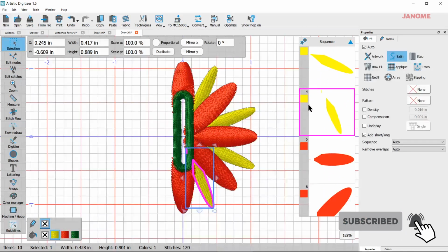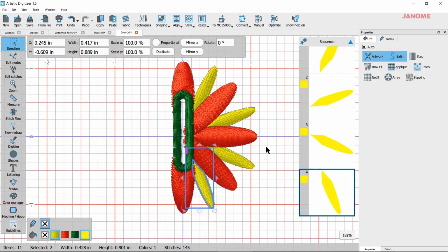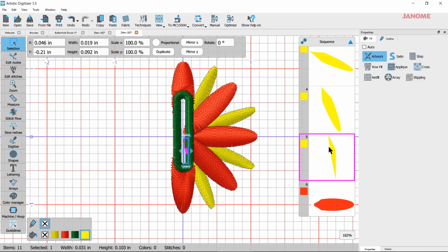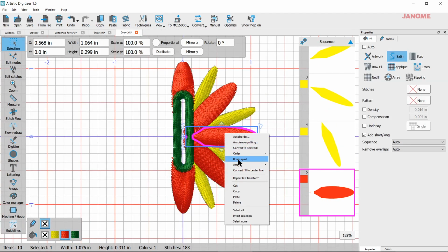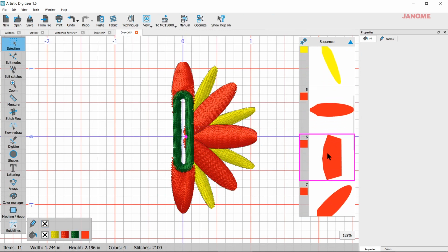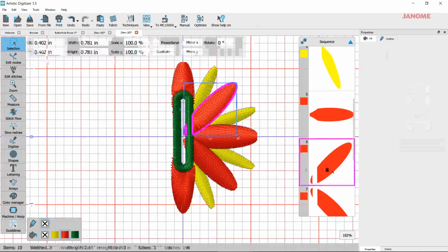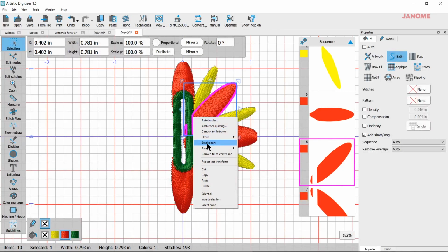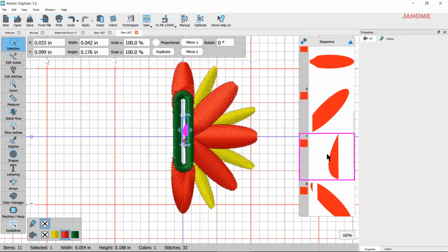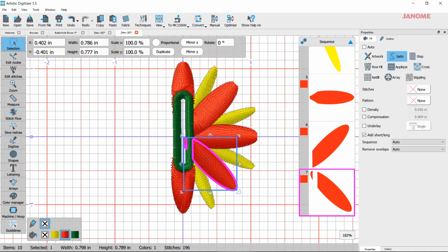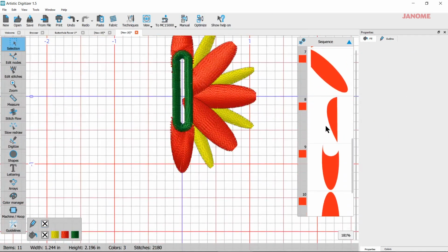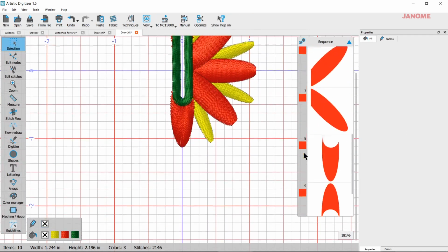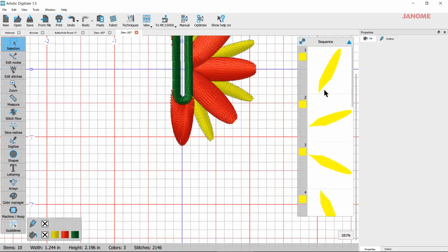This one has a little extra piece. I can see that. I'm going to right click on it, break apart, click off of it. Then I can find that little part and delete it. Same thing here. Right click, break apart, come in here, delete that little section, come in here, break apart, delete that little section. This last one, I think this is my last one, break apart, come down here, select that, and delete. And so all those little parts should be gone now.